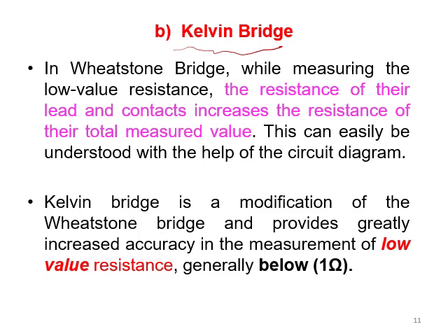You remember that we are dealing with instrumentation. Instrumentation means the things are sensitive. I mean, we are very much concerned over small values, the small changes. That's why sometimes I need to calculate the small resistance or small change in the resistance. So if the resistance is less than 1 ohm, how can I measure it? Actually, the difficulty will come when I want to measure a resistance lower than 1 ohm. Why is measuring less than 1 ohm difficult? Because the wires used to measure the resistance themselves have resistance. So the resistance of the wire will make error in the measured value.